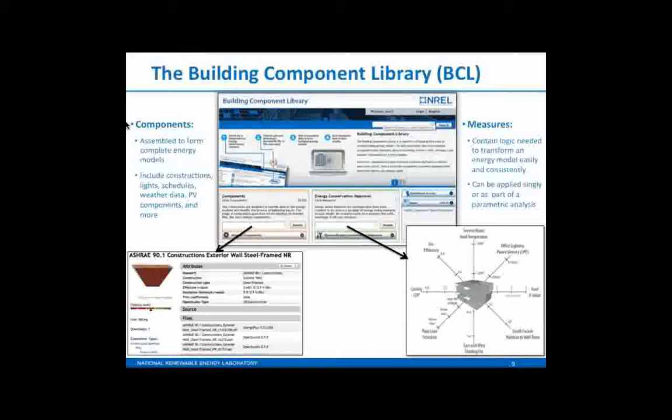So again, it's that notion of repeatability. You can apply a measure to one or lots of buildings, or a whole suite of measures, and that's pretty much what the cloud analysis tool is all about. It's saying, well, I want to look at the interaction between window-to-wall ratio and insulation rating and building orientation. Maybe it's just those three things, and you want to rotate your building in 10-degree increments, or change the R-value in a certain number of steps.